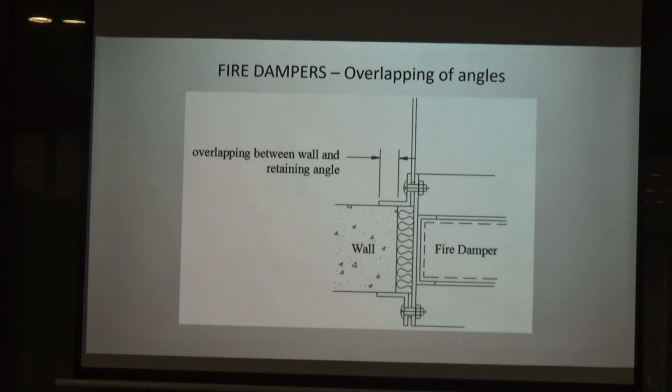Because for normal cases, contractors usually open 20 to 25 mm all round, just to slot in the rock wool. So what if the opening is less than the standard minimum opening? They're not sure that they have to hack or something. By right, by right, they have to make sure it is big enough.